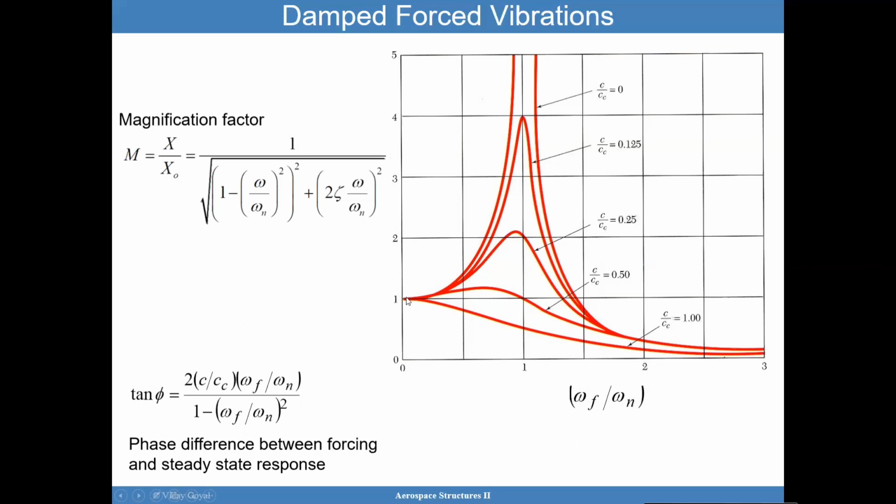And so that's very useful. It allows you to focus and figure out, do I really need to apply dynamics here, or can I get away with a static solution? This kind of plot can be very useful. Now, when you get to a forcing frequency that's close to the natural frequency, you get peak response. And again, with no damping, this goes to infinity, and we discussed that earlier.